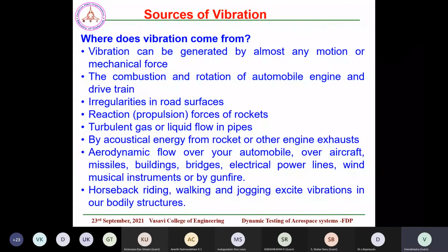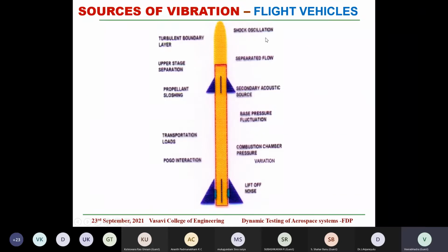In typical aerospace industry applications, during liftoff you get a shock or noise, and due to the propulsion you again get vibration. Again, due to the aerodynamic noise, we get a lot of vibrations, and the external surfaces also get different vibrations. And if it is liquid propulsion, you even get sloshing and other interactions like pogo oscillations.